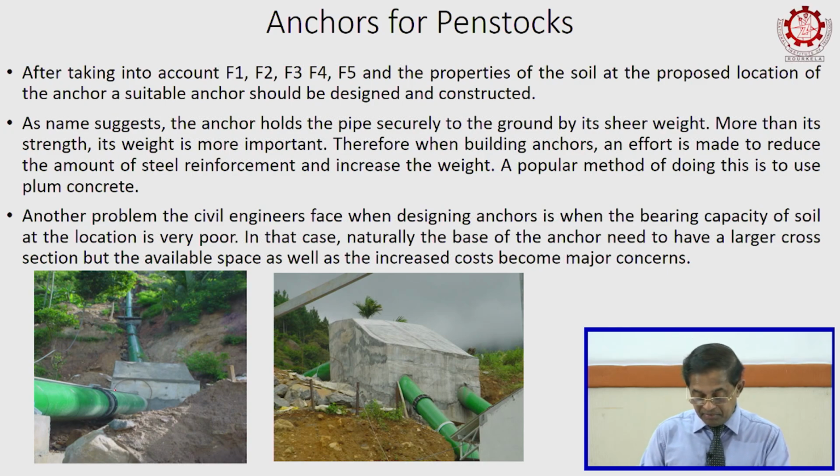Here is a large anchor, as you can see, because at this place the soil was very bad. So, we had to design a large anchor to increase the cross sectional area of the bottom, so that the earth can bear it, otherwise it will go down, right. And also the bend was big,